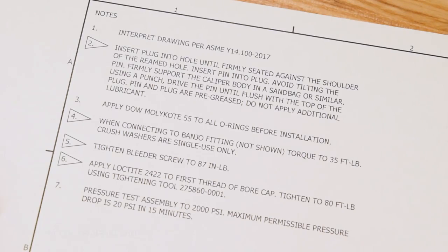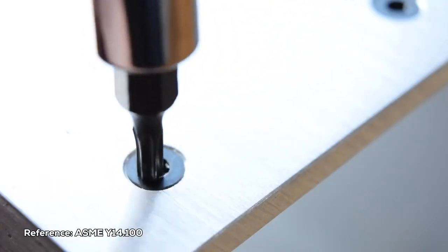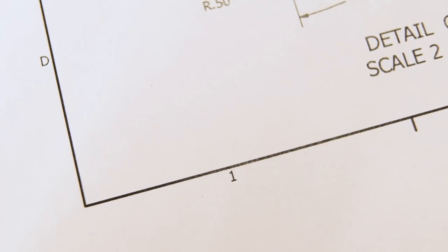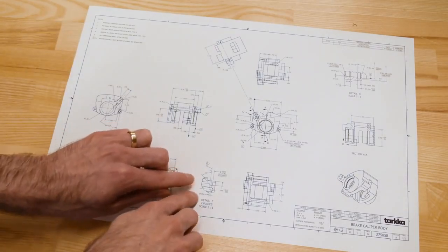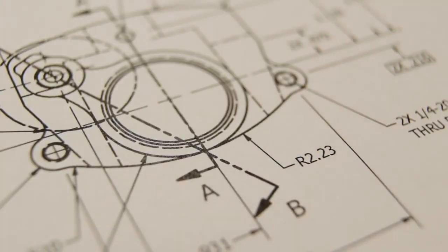The notes list provides information like the material and coating specifications, relevant standards needed to interpret the drawing, special instructions for manufacturing certain features, and other information that can't be conveyed with a dimension. The border defines zones with letters and numbers that allow you to identify specific features with coordinates. This is really handy on big drawings because you can say something like, change the 0.19 hole diameter in zone A7, and be able to jump right to it, instead of having to scour the entire drawing to find something.